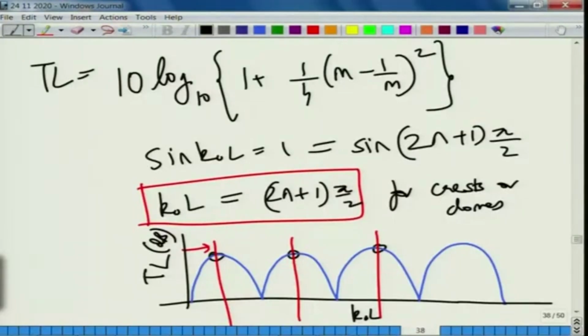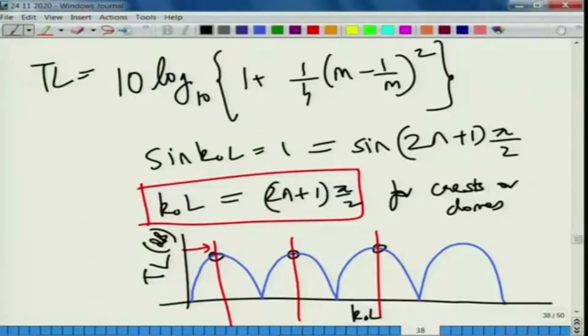Like this, the pattern keeps on occurring, but what is more important to all acoustic designers, for a muffler designer, is basically where the trough occurs. So, where does the trough occur? What do we mean by a trough? By trough we mean where the transmission loss is 0 or probably a minimum, so that almost all the acoustic power goes away. So, now let us look at this figure. If you look at the transmission loss graph, wherever this, let me use a different color, maybe purple.